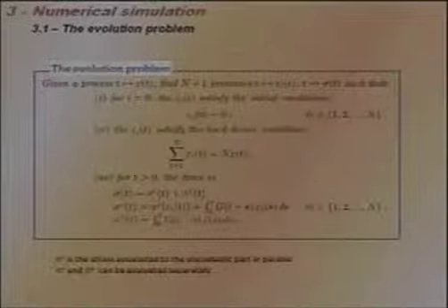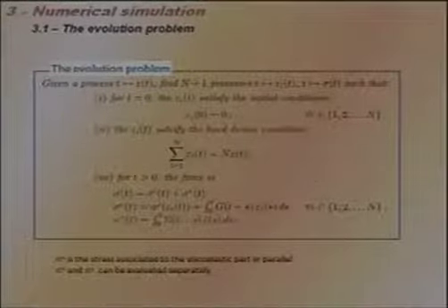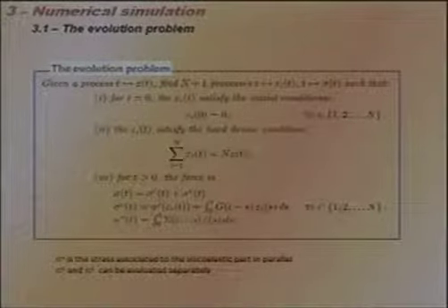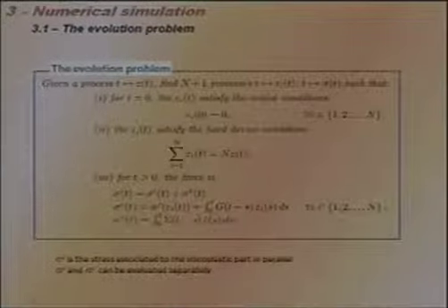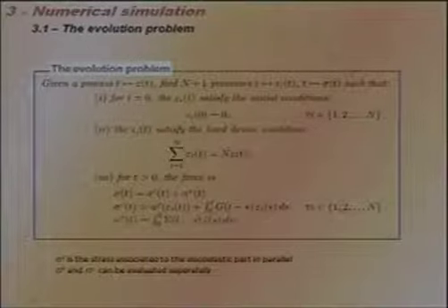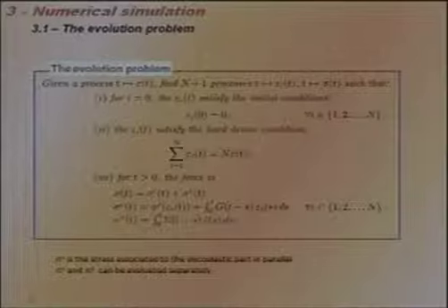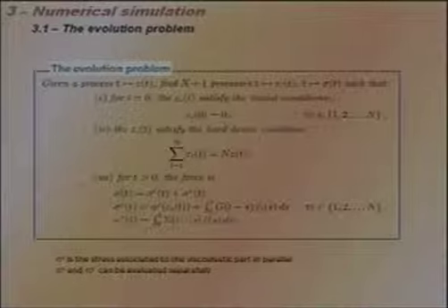So, what is the problem to be solved, and how do we solve it? The problem to be solved is that one. We have this condition that all the layers share the total deformation, that the stresses relate to the parallel modulus, and that relates to the nonlinear part and the viscous part.